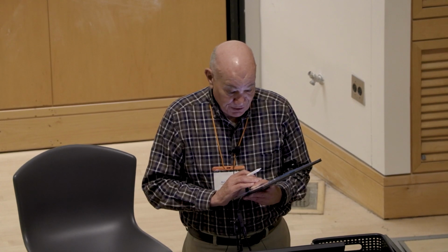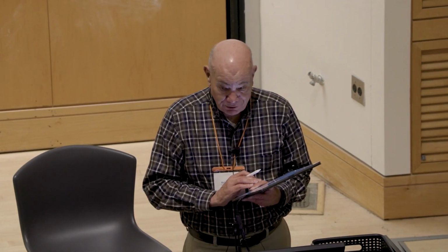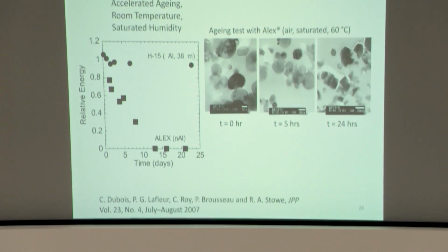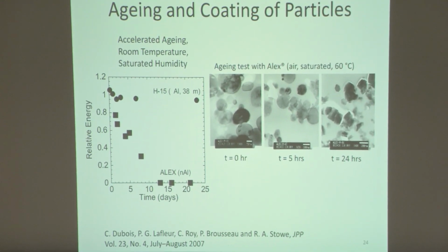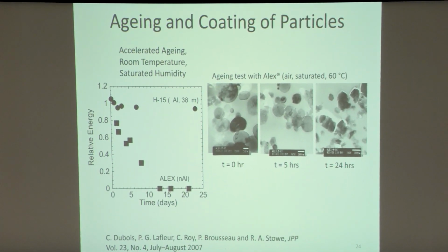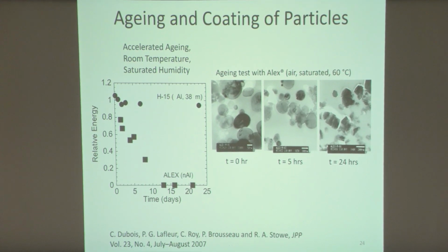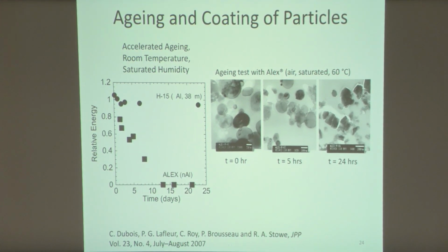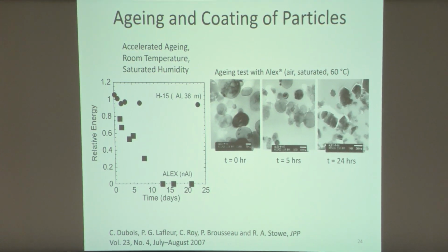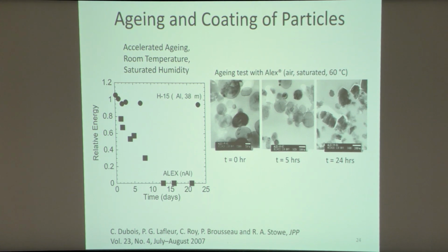Okay, a couple other things you've got to realize about nanoparticles. Because they're very small and the oxide layers are thin, so I have small length scales, they can age much more than micron particles. Any little reaction at the interface, if the particle sits out on a shelf and it absorbs moisture, it has a lot of surface area, it can actually age the particle.